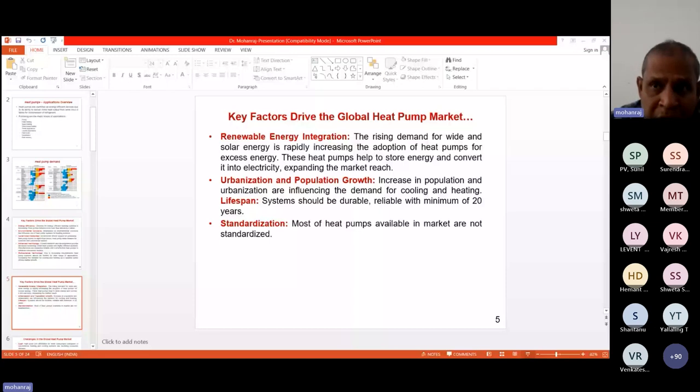But the Chinese introduced these refrigerant compounds, but it is not going to be a sustained option for a long time. It's an interim option. So identifying a proper refrigerant for a heat pump is itself a major task which you're going to face in future. For small capacity heat pumps with less than 10 kilowatt, we can recommend propane as a good option.